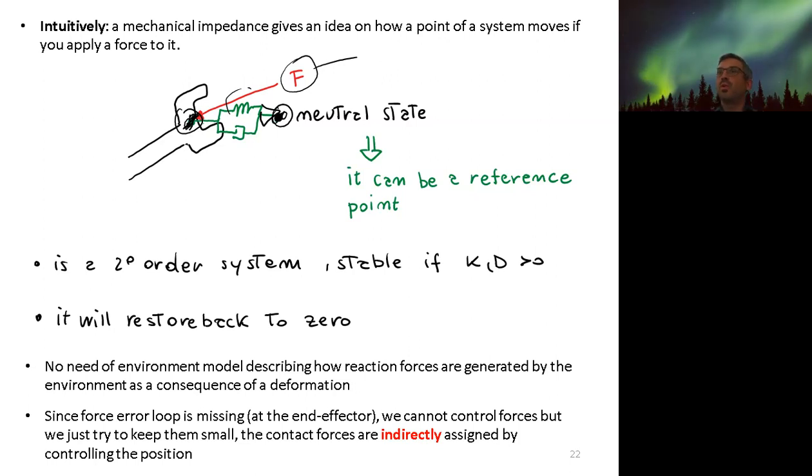Remember, all our control laws are setting a desired torque for the robot. So we need to think that the impedance implementation will also send the desired torque to a low-level torque controller that runs at the joint level. So there is a loop closed on the torque, but at the joint level.